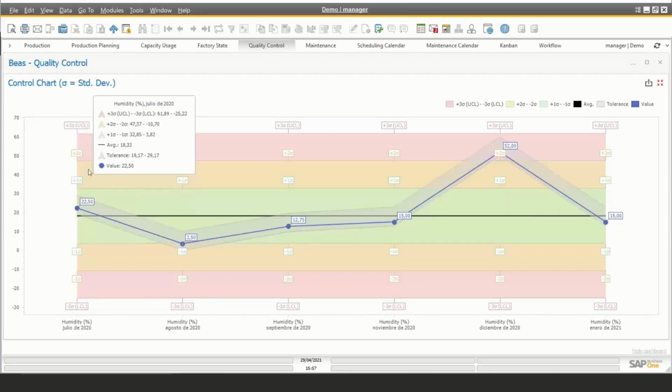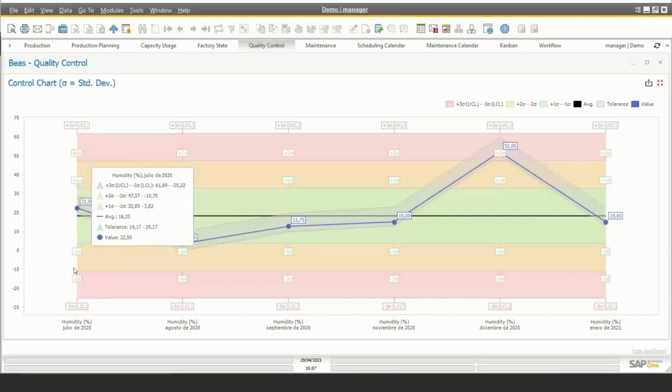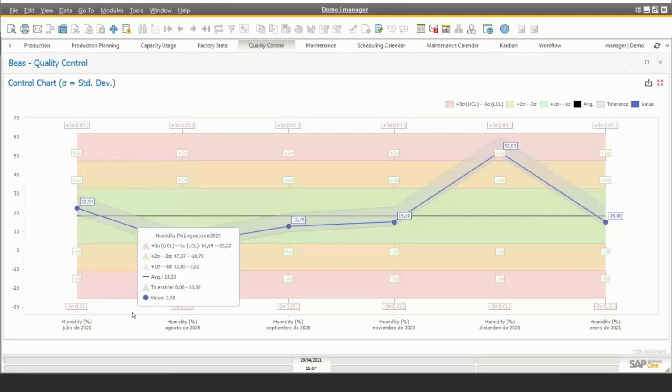We basically have +3 deviations up and -3 deviations down. This will tell you the safe ranges that you can have for not going too far from your control line. And in the moment you see that you are going too far, then this can also be an alert for the quality control persons to know that something might be going wrong with that kind of inspection.